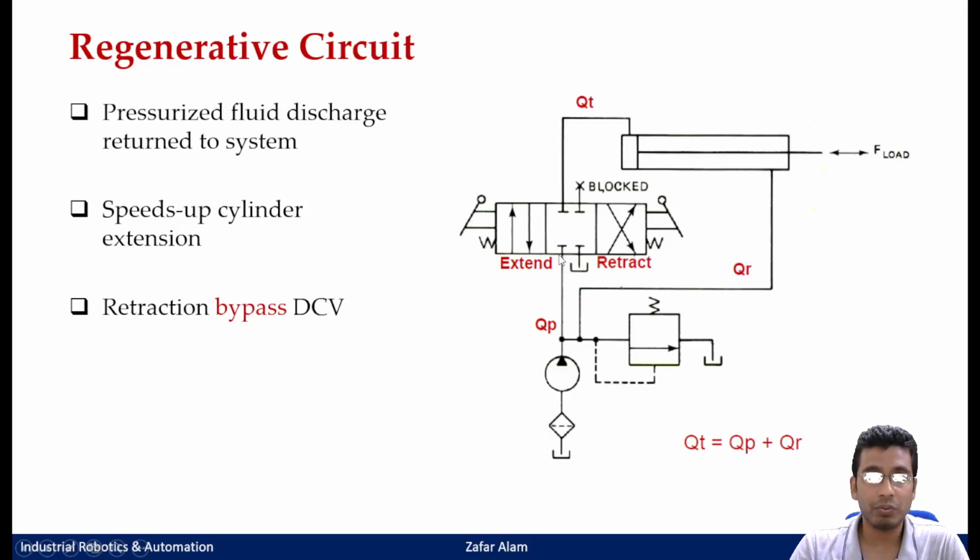That means when the cylinder is extending, just say this is your extending envelope of your valve. Whenever you put the lever forward to engage this envelope of your valve and your cylinder extends, your pressurized port gets connected to your A port here, and this arrow is connected, so your cylinder starts to extend.